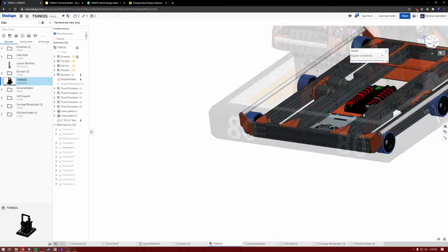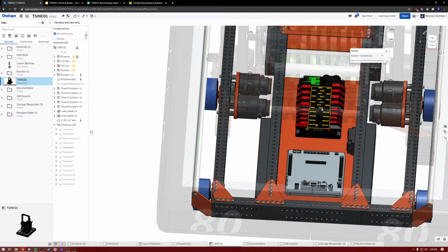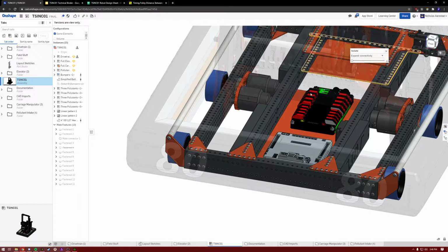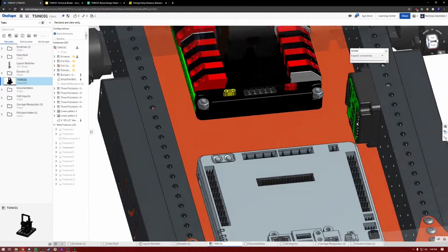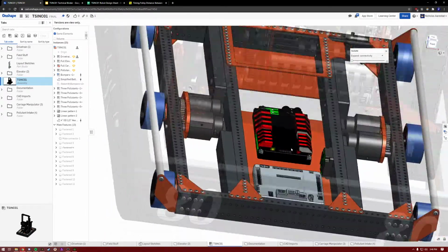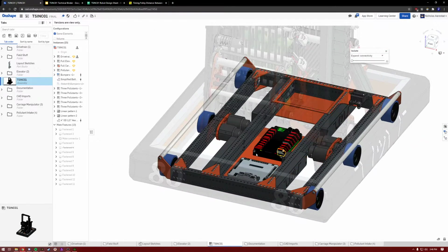One of the other big things you'll notice in here is we've got the PDP really close to the battery. This is a really good design feature. We've got VRM down here and not a whole lot else. A lot of the electronics on this are the motor controllers that are out close to their motors, because they're Spark Maxes, and you want to keep those within the 12-inch wire length coming off of the motors that they drive.